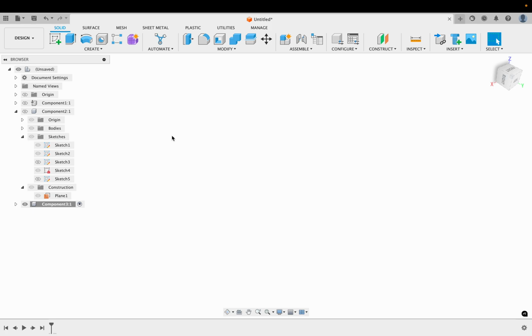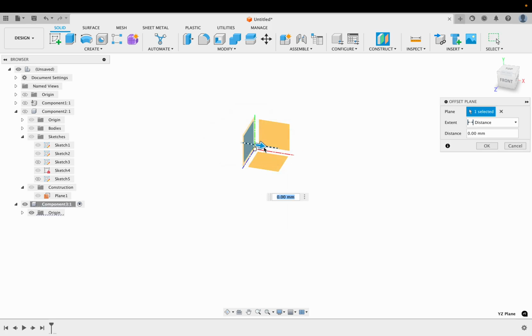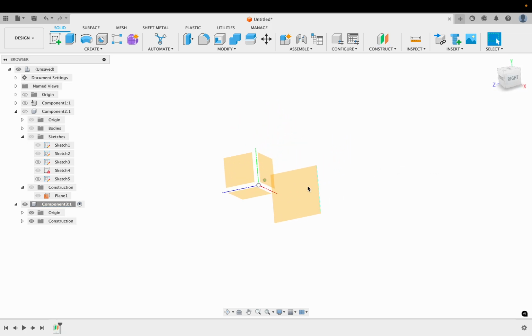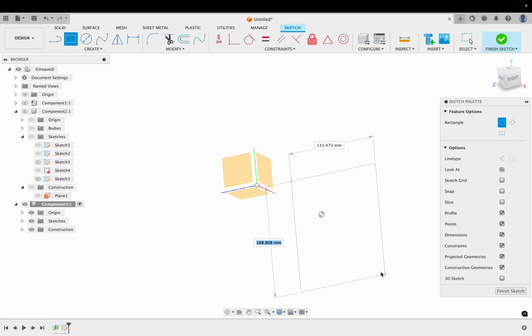So, headphones. Let's make some sort of cup. And I argue that we should not place one cup at the center, so I'm going to have to live by that. Now I'm looking at the front, that's the left, so maybe that's the front, so my cup should be out here. So the first thing I do is offset that plane and move it out here. I don't know how wide a head is, but let's say we move it by 200 millimeters. And then I can make the contours of a headphone cup out here. Maybe it should be very crude and square-ish.